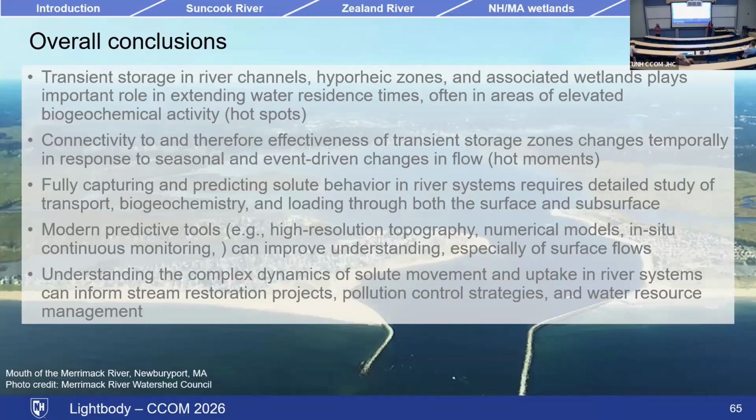One of the reasons that Ryan is really trying to do grain size for the Zealand, which is a cobble bed river, is that it varies, and there's a huge impact on the hydraulics depending on where it's more gravelly, with no sand in there, or where it's a bigger cobble boulder or a smaller gravel. So you try to do it spatially varying. So he's doing spatially varying drag.